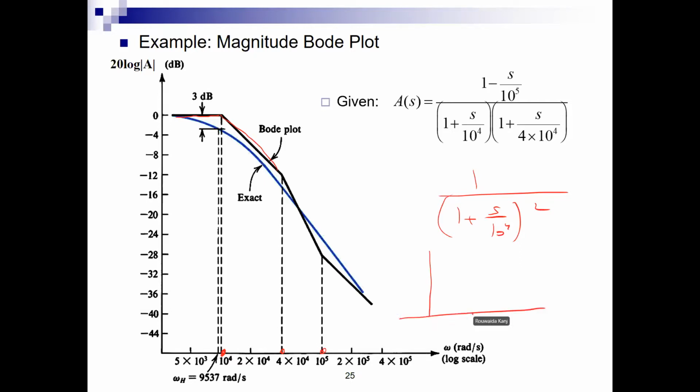By 40, right? And that will go down with a slope of minus 40, right? So the exact 3 dB frequency happens to be here. And I know if I operate before it, my gain will be almost very close or reasonably good. Okay, so the two things are different. Do not ignore anything in the Bode plot, okay? Okay. Anybody else? Thank you. Anybody has any other question?